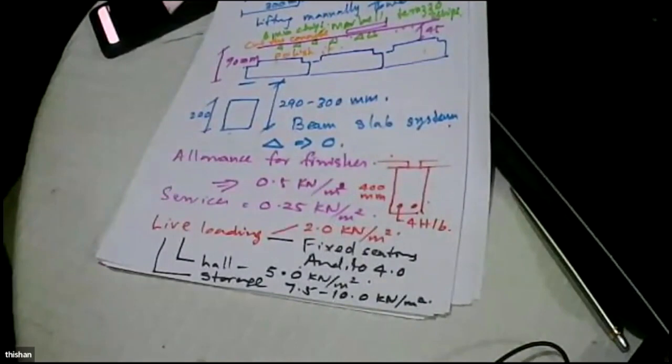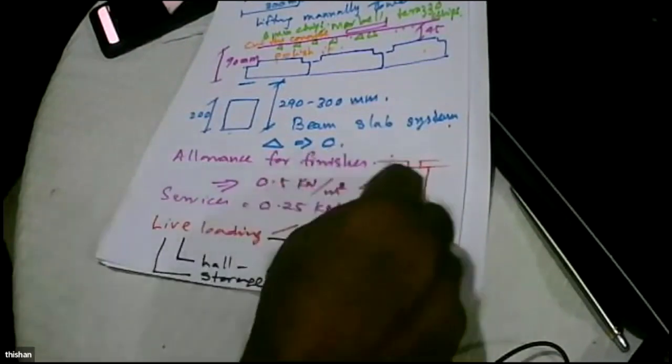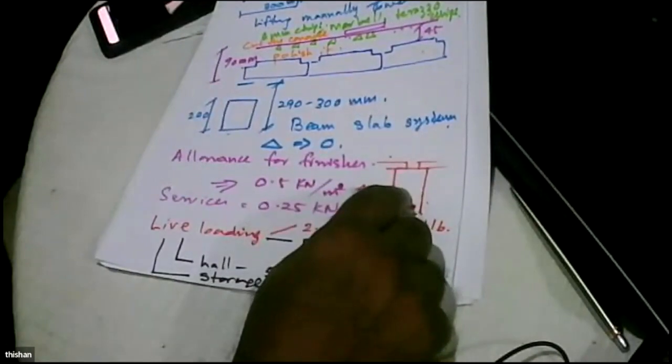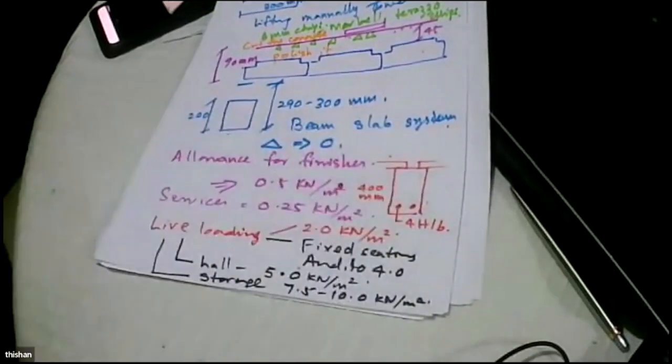And then there's another trick. You think this can be overloaded. What we can do is, this beam, we can have another span, but they are cast as simply supported. So at the site, we can make them continuous. So there are many options that are practically possible.